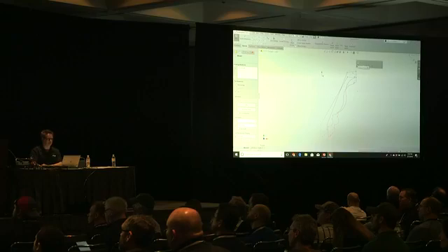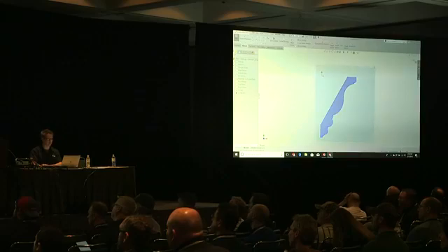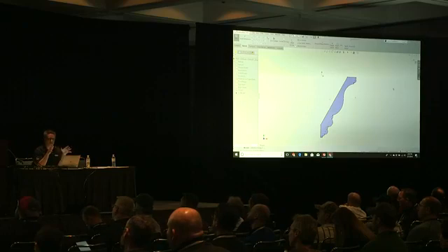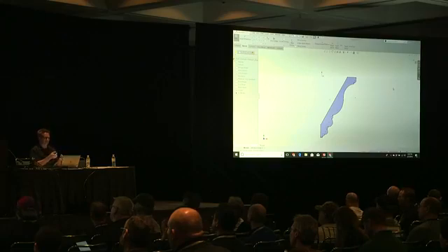Because I get this, I go horizontal. Now I'm really going to mess with you. Explode the block. Now we're all back to underdefined geometry. Window around all of it, fix. That all seemed really goofy, but the whole idea was I want their geometry in the way I want to see it. It's fully defined. I don't need to add dimensions because I'm buying something stock and off the shelf.